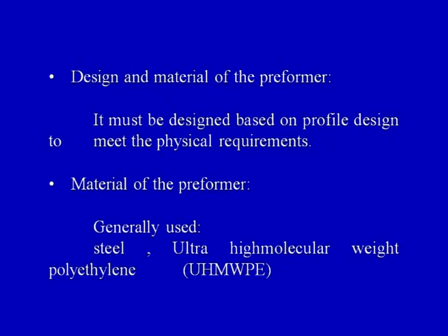Another important point that has to be taken care of is the design and material of the preformer. Now it must be designed based on profile design to meet the physical requirement. So the preformer, as we already have seen in the diagram also, gives a rough shape to the fiber and the resin system before it enters into the die.